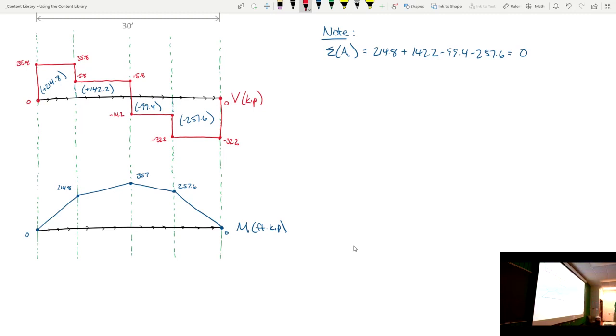Now, if I integrate y equals 6, what do I get? Integrate, not differentiate. What is the integral of 6? 6x plus c, right? The integral of any constant is that constant times x plus c. The integral of a constant is a line. So that's why for every one of these constant shear regions, we get linear moment regions. That's why they are lines.